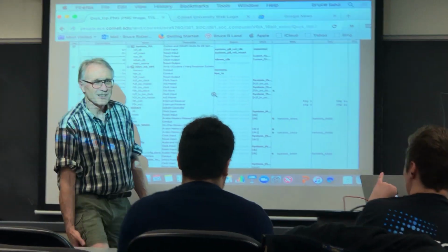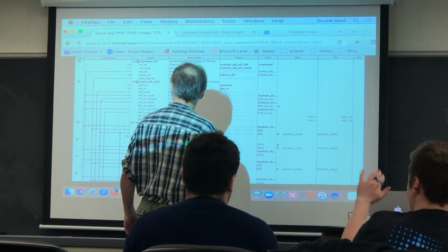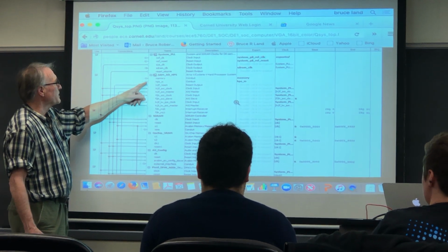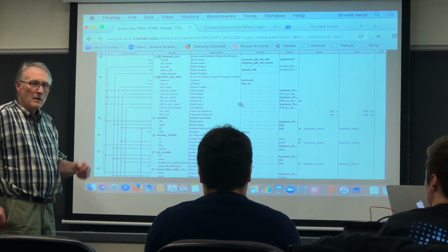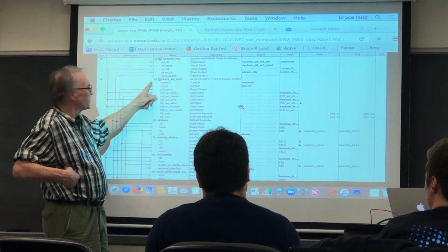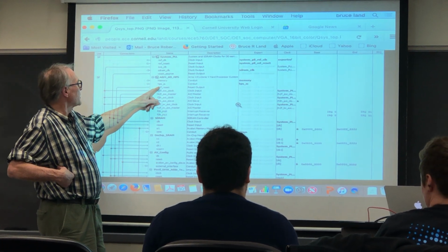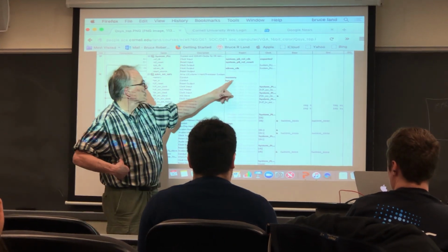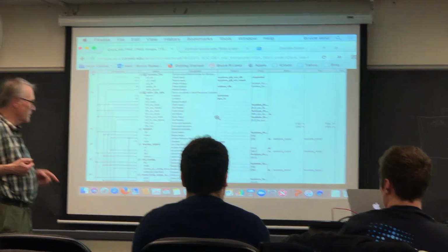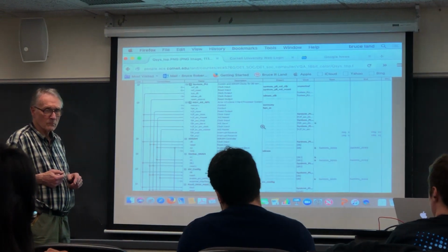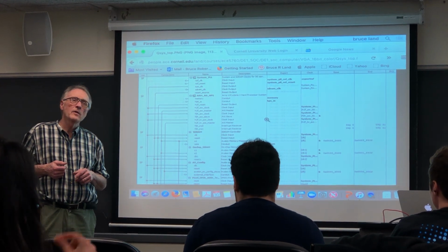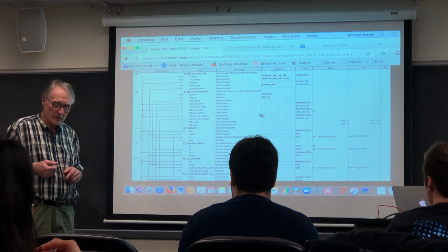So are the little rectangles where it just comes out into the connection? These little guys here, is that like an external interface? These are just non-connected. This particular connection was exported instead of connected on the bus, and so was the HPS I/O, exported to the FPGA rather than connected on the bus. Can you both hook the signal on the bus and export to the FPGA? Depends on the wire. Generally, yes.